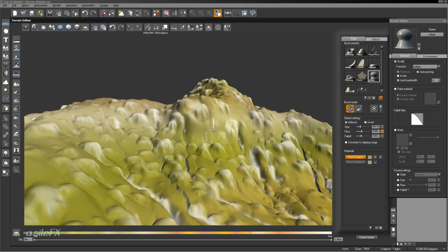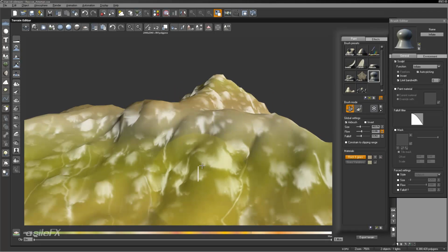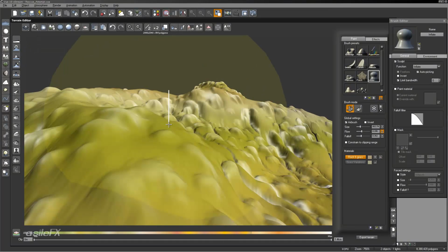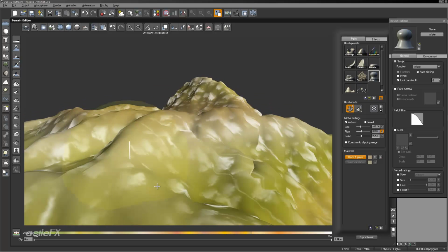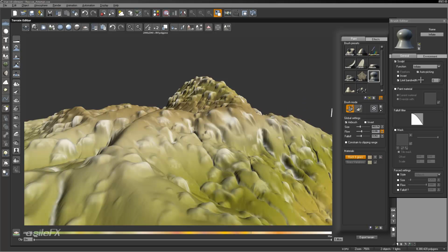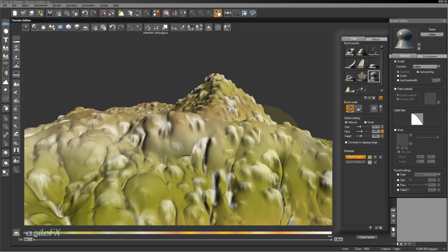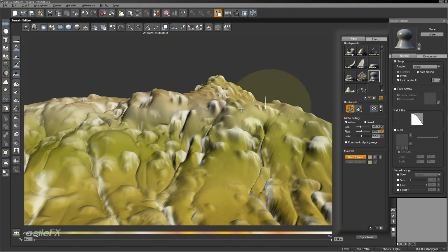So when we set the bandwidth, we can choose our layer, and it looks like 8 million is going to be the minimum because of the scale of this terrain. But what we can do is adjust which layer we're working on and what resolution. So right now, I'm not working or painting with the full 8 million. I'm really working with a lower resolution layer, just bulging out some of those areas. So if we want to increase the level we're working with, we can set it to 1. And actually, if we turn that off, we should be able to work with something a little better. And it looks like that's just because we really only have one layer of detail.